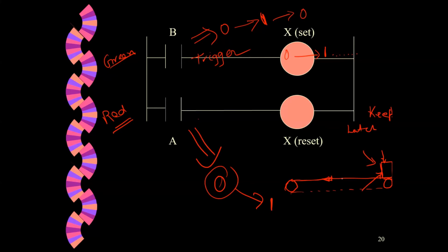Now this conveyor is stationary. Okay, then once the box is present, let's call it A, and it is full, A and B, and let's call this a motor. I'm close to the area of my tablet. If A and B is true, turn the output M. So the motor will start moving and the box will be transported.